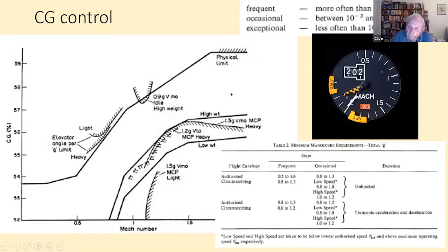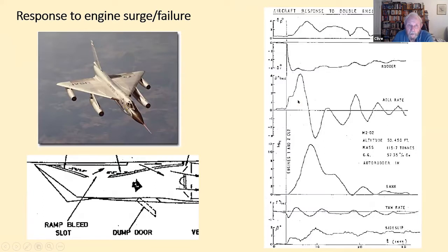In order to help the pilot with that, the Concorde Mach meter has an extra function, which you don't see in others. Not only does it indicate the Mach, but there is also a center of gravity indication on it, with the forward and aft range of CG for that particular Mach number indicated, and a pointer which actually tells you where you are inside that range. So in this particular case, the airplane was about there. As I say, that one is peculiar to Concorde.